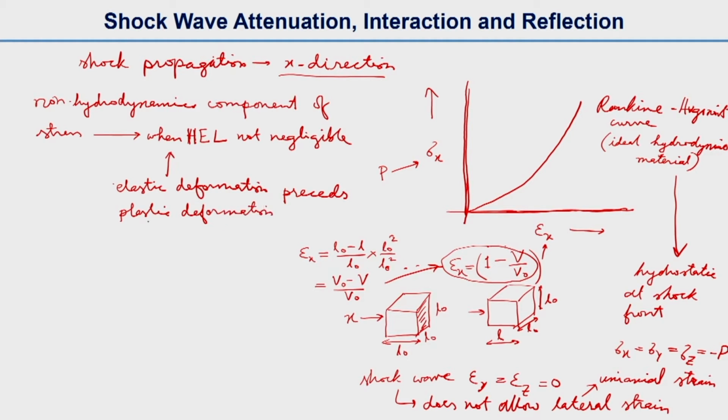And as you know, this plastic deformation happens when the shear stress tau is equal to tau yd, that means the dynamic yield shear stress. That is shear stress, not the normal stress: the dynamic yield shear stress.